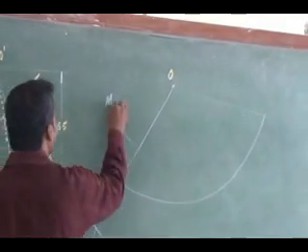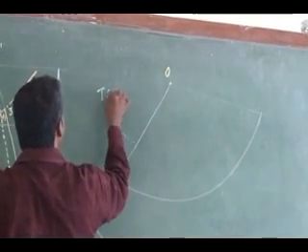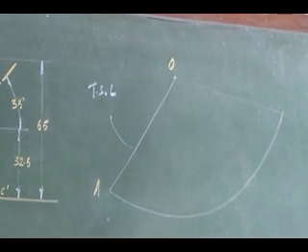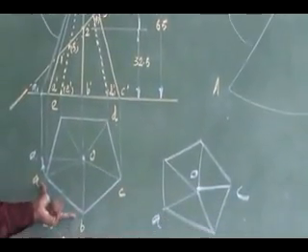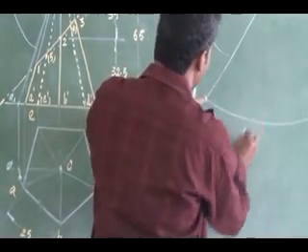This is my measuring length, true slant length. Slant length, right, OA. Now, after that, you have to measure this base side, 25. In your compass, you get 5 divisions, 5 segments.